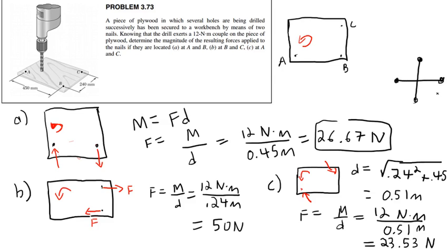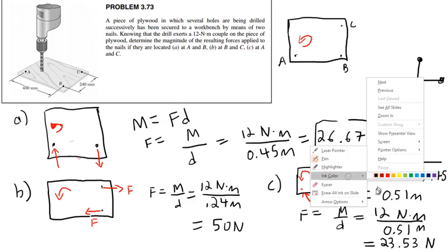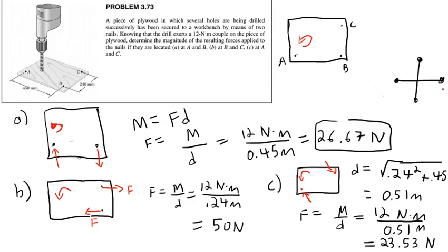You're going to apply a force, say, this way, and this way, this way, and this way. That would be to tighten it. To actually loosen it, let me draw this in red. To actually loosen the tire iron, we want to make it go counterclockwise, sorry, obviously. So we want a force like this, and a force like this. Oh, actually that will loosen it. Oh, not thinking right. So yes, we want to apply a downward force with one hand, an upward force here with our right hand, and a downward force here with our left hand, and that will generate the moment needed to overcome the resistance in the bolt. Okay?